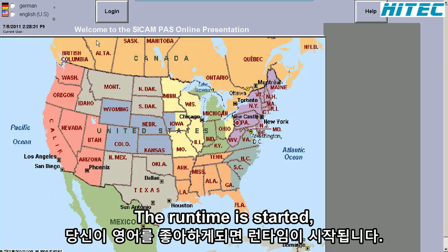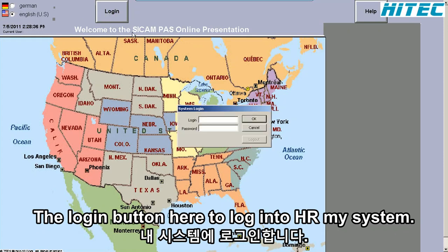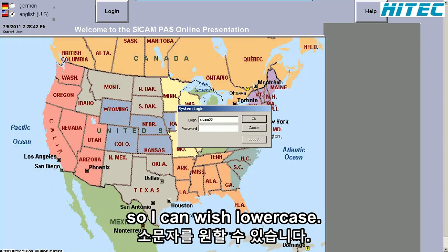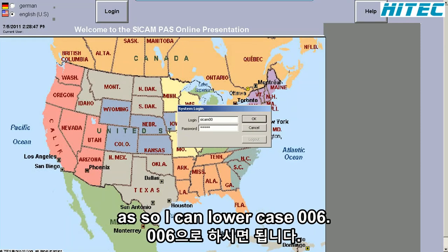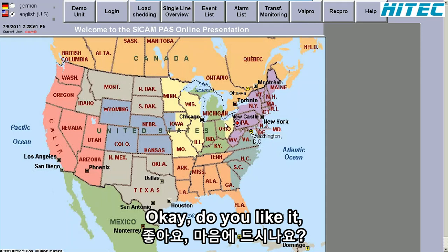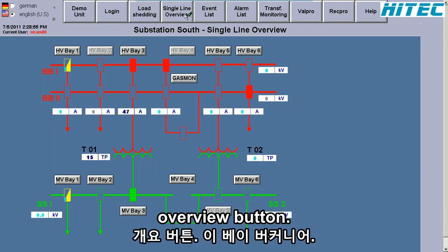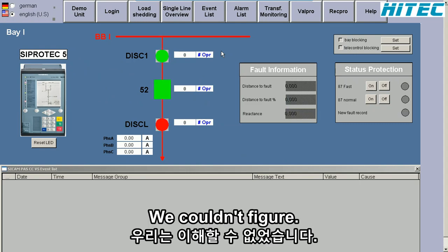The runtime is started. You can select English US and click the login button here to log into the HMI system. The login name is SICAM00. SICAM is lowercase, and the password is exactly the same as SICAM lowercase 00. You click OK. So now we're logged in. If you now go to the single line overview button, this bay button here, bay 5, is our first relay that we configured.